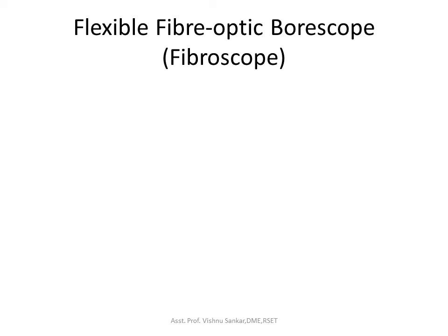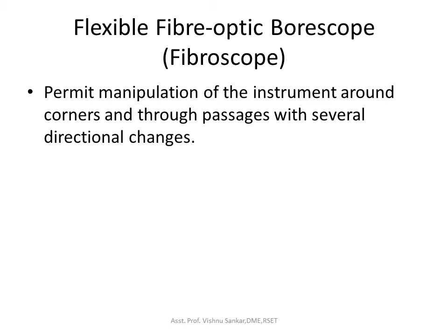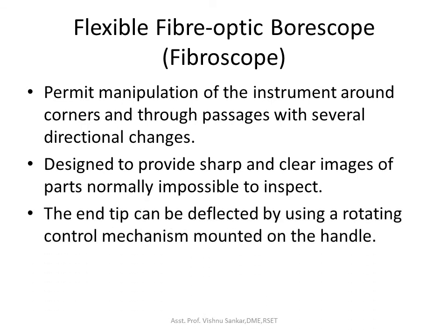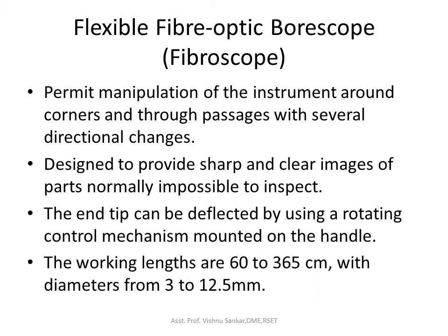Now, what is NDT, non-destructive testing, or NDE, non-destructive evaluation? Technically, NDE is used to describe measurements that are more quantitative in nature. An NDE method would not only locate a defect, but it would also be used to measure something about that defect such as its size, shape and orientation. NDE determines material properties such as fracture toughness, ductility, conductivity and other physical characteristics.